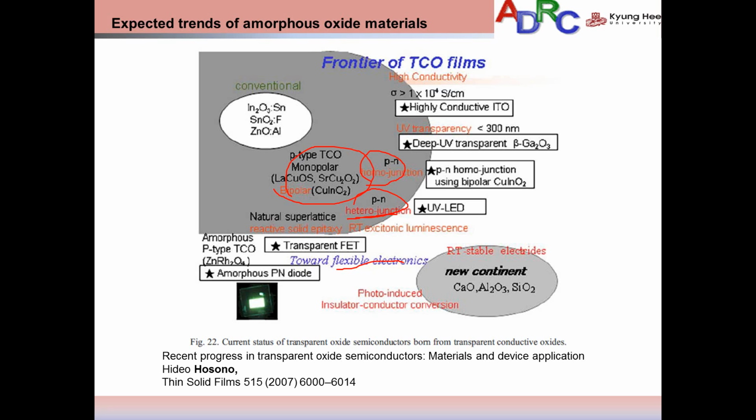So we want to do amorphous oxide semiconductors, but also oxide conductors with a high conductivity. The one which is used mostly is ITO, and the main idea also, if we want to make very highly transparent material, we need them to be over 80% transparent in the visible region. And this is the case for most oxide semiconductors, because their band gap is very high, very big.